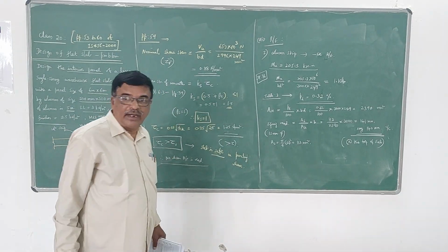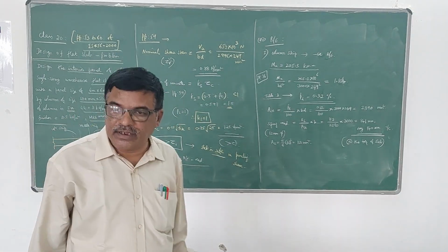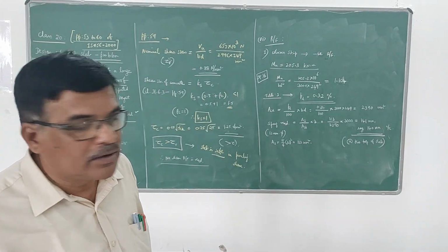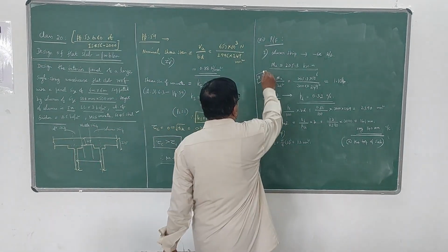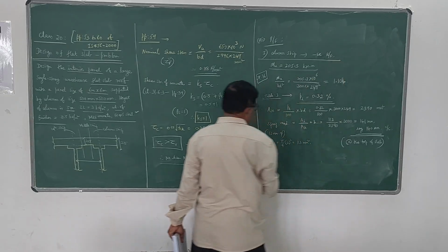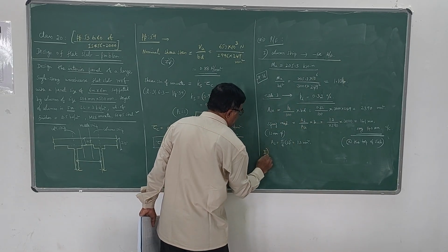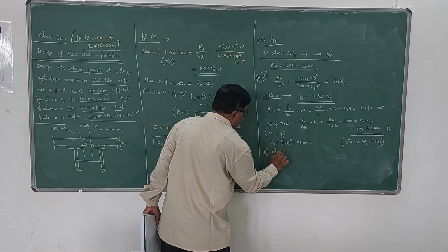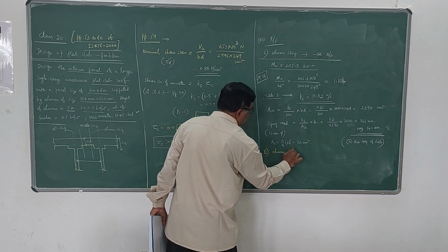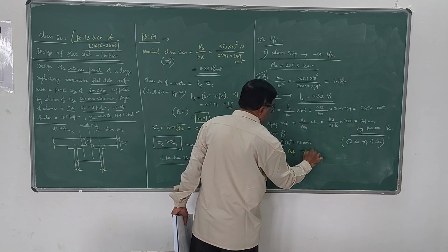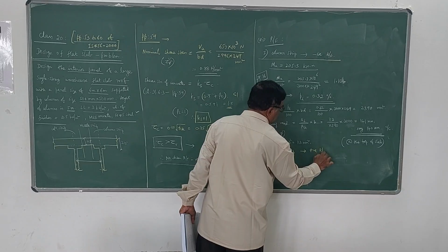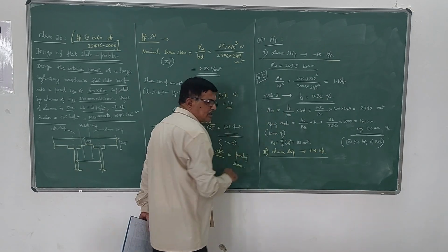Similarly, we have to calculate the reinforcement for positive bending, and the same procedure is adopted. I have taken the first case like this. Similarly, the second case will be the column strip only, but with positive bending moment, that is, positive reinforcement.